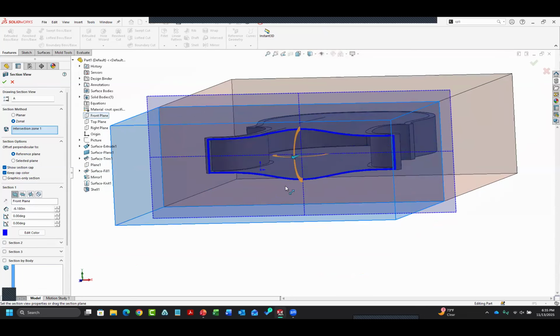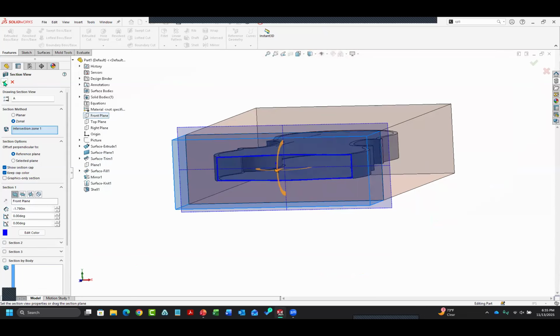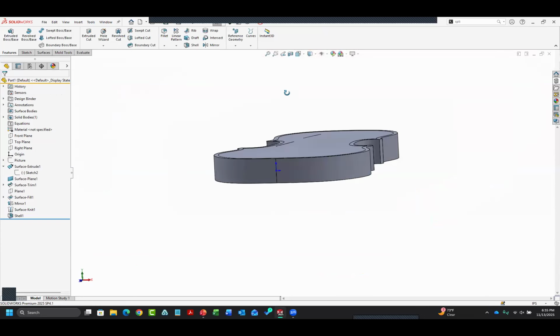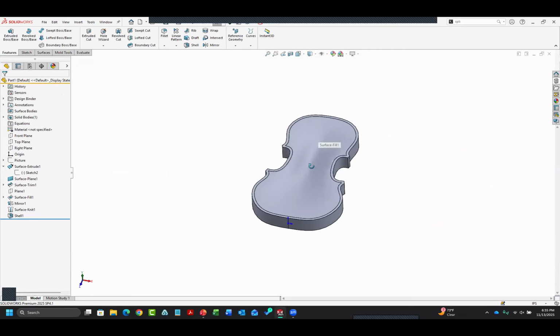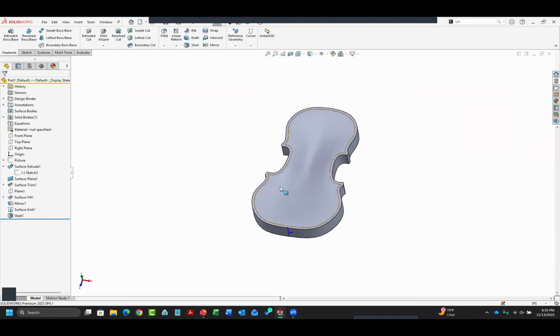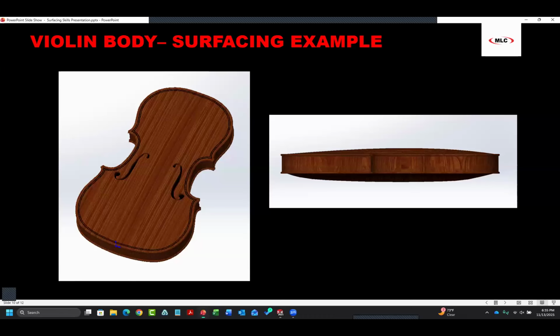So again, not a lot of real flat surfaces that we created, but I gave you some tips there on how to kind of get started sketching over those pictures and how to set up the filled surface. So filled surfaces are great when you have a distinct boundary, and then those contours in the middle can give you that additional shape. So I'm going to kind of wrap it up here.